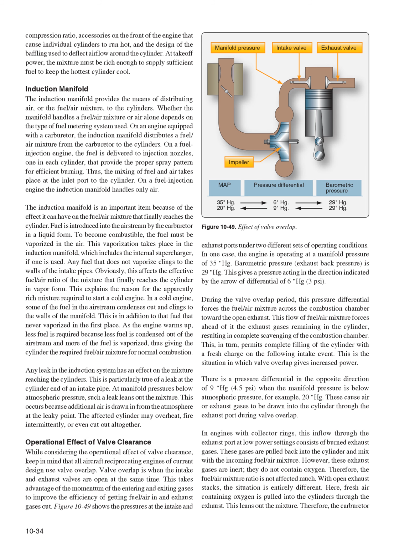Operational effect of valve clearance. While considering the operational effect of valve clearance, keep in mind that all aircraft reciprocating engines of current design use valve overlap. Valve overlap is when the intake and exhaust valves are open at the same time. This takes advantage of the momentum of the entering and exiting gases to improve the efficiency of getting fuel/air in